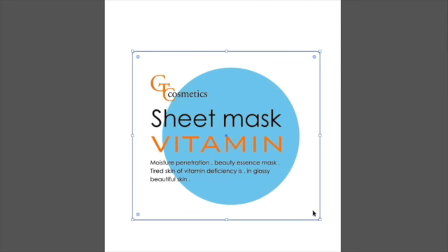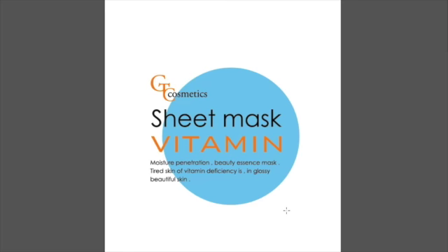In cases of making a decal, you may decide that a cut line that contours the graphics design is the best choice. For instance, here we have a design that we can use as a decal. Here we'll create a cut path that contours the design. While we will be using Adobe Illustrator, CorelDRAW has similar steps to create the same kind of contour cut line.